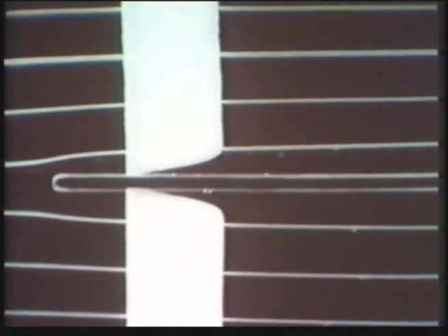Upstream, the velocity gradient is fairly large. Downstream, it is much less. This composite photograph compares the two velocity profiles. Because there is no vorticity upstream of the plate, and because the circulation per unit length along it is constant, we conclude that all of the vorticity in the boundary layer is introduced at the leading edge.